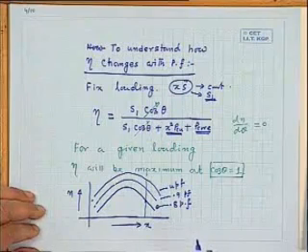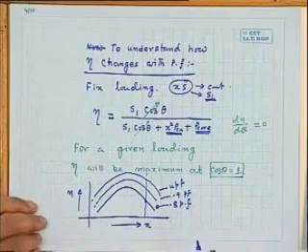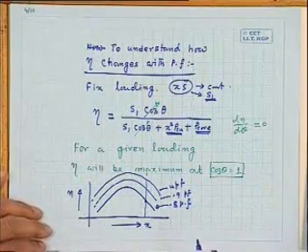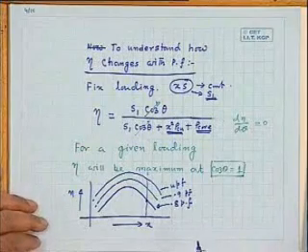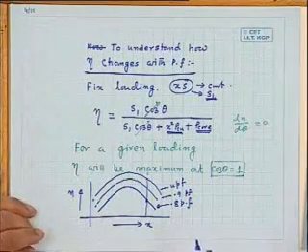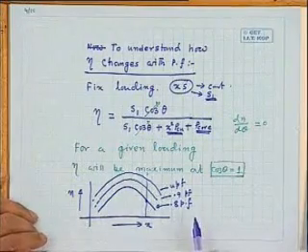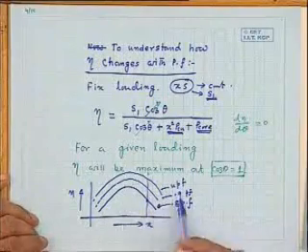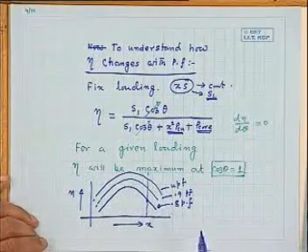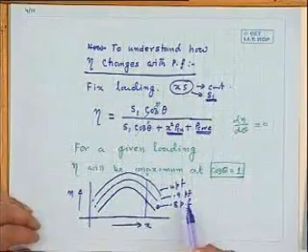This is suppose unity power factor. Okay. Anything? Sir, from the expression of x, we see that it's given by square root of P core by P copper. Right. So, is it necessary for all transformers to have P core less than P copper? At that point, I am just coming. So this will be the thing, efficiency versus x curve for different power factors.